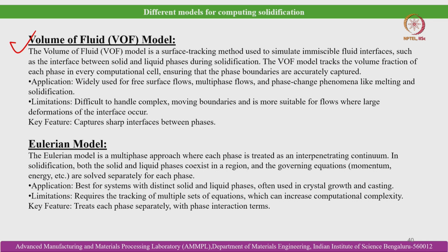The main thing is that it basically solves the governing equations of conservation of mass, momentum and energy. Even if it is a multi-phase flow problem, it solves only one set of governing equations. So it is kind of a mixture model. It does not solve separate equations for the individual phases present in that multi-phase fluid, whereas the second approach is the Eulerian multi-phase flow approach.